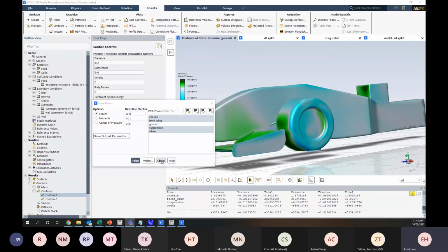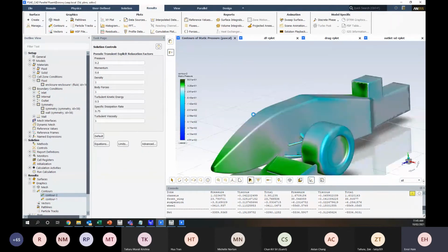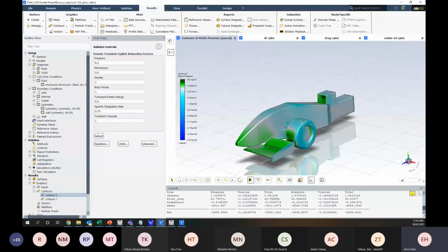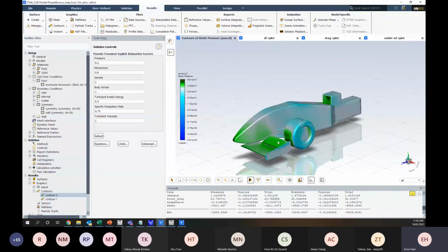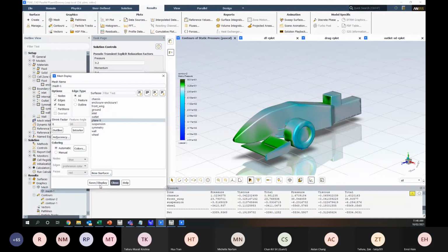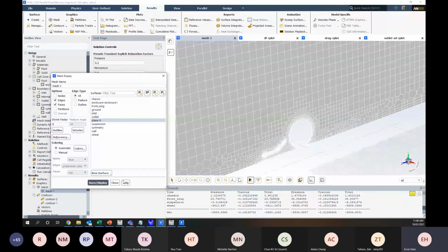Can we set up a turbulent kinetic energy plot to assess if the inflation layer is capturing the boundary layer? Yes, we can. I'll show you exactly how to do that. So one place we might do that is on this front wing. So we look at the bottom layer of the front wing. Just see where this plane is. Yep, that's where we want it.